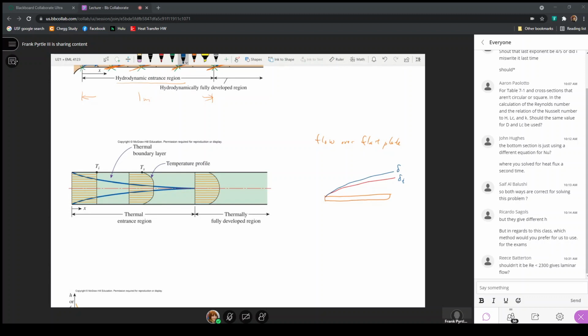where the black line is the inner surface of the pipe. Now, if I have a constant heat flux coming in from the surface of this pipe into the fluid, the temperature of the fluid is going to keep increasing as I apply a heat flux into the fluid.